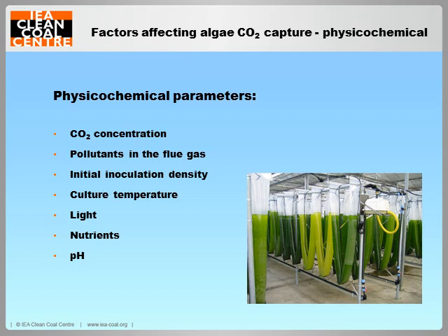Room temperature around 18 to 20 degrees is often recommended, so flue gas needs to be cooled down before pumping into the algae culture medium. Usually, low pH value reduces algae's growth rate. The pH in the culture medium depends on the carbon dioxide and the sulfur dioxide concentration in the flue gas.